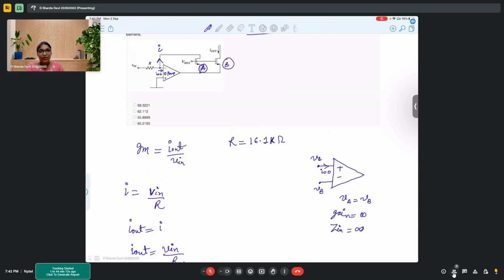First of all, for an ideal op-amp we use the condition that there won't be any current going inside the op-amp. So that's why we didn't have to use any KCL at this input point of the op-amp. We simply use the current. After that, you can see that they are like mirror circuits, since their VG and VS are connected together, so making them matched.